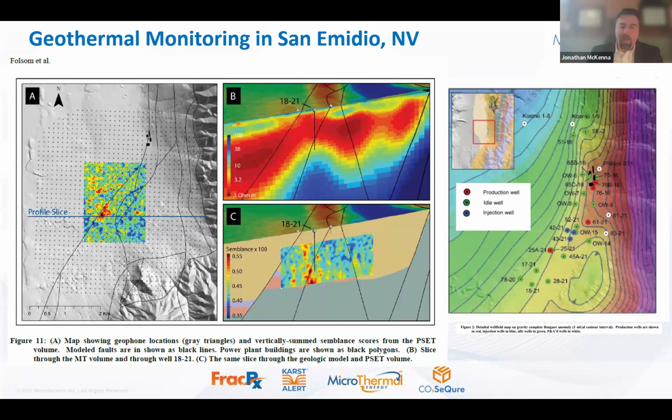Yeah, that's a great question. So, typically, the more DFITs that we can get, the better. A DFIT will tell you how much fluid is leaking off into the formation. And so if we're stimulating different levels, we like to have at least different DFITs at different levels, if not different DFITs throughout the system.